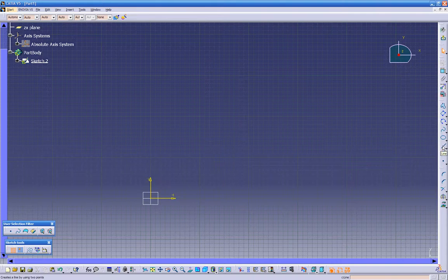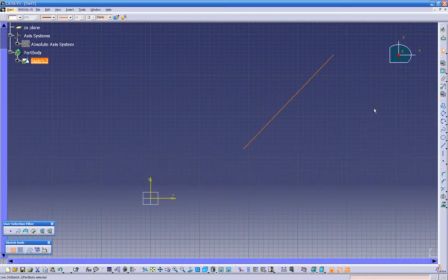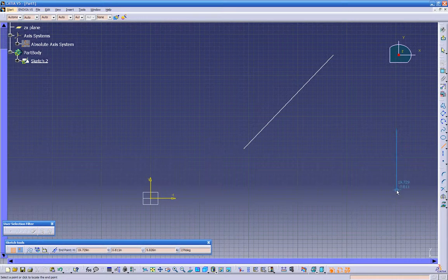But let me show you this quick. This is pretty handy. If you click on this icon only once, and you click on the line, you just create only one line. You cannot go any farther. See, this deactivated. But let's see, if you double click on the icon, create one line, you can keep on going.